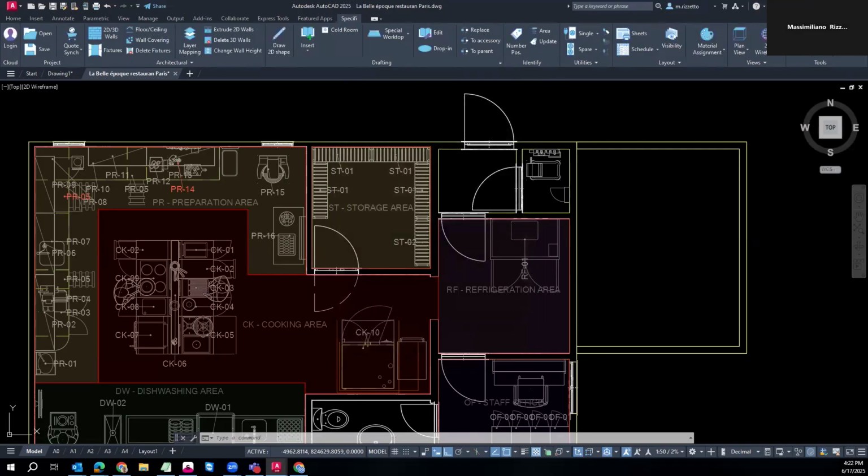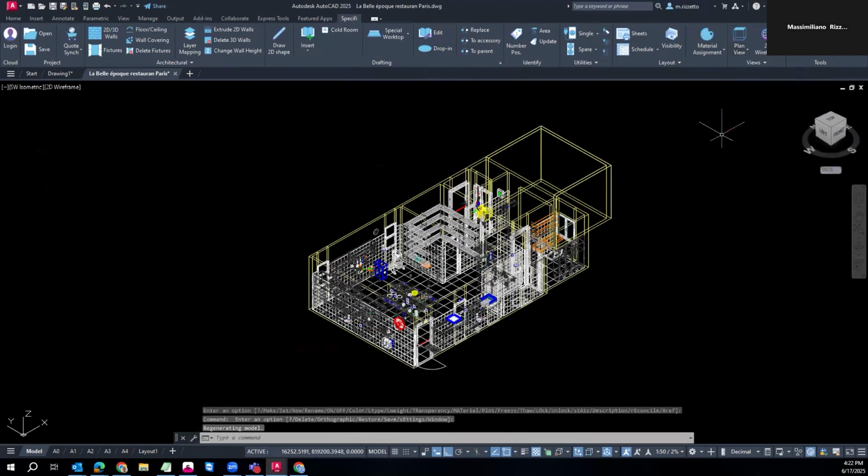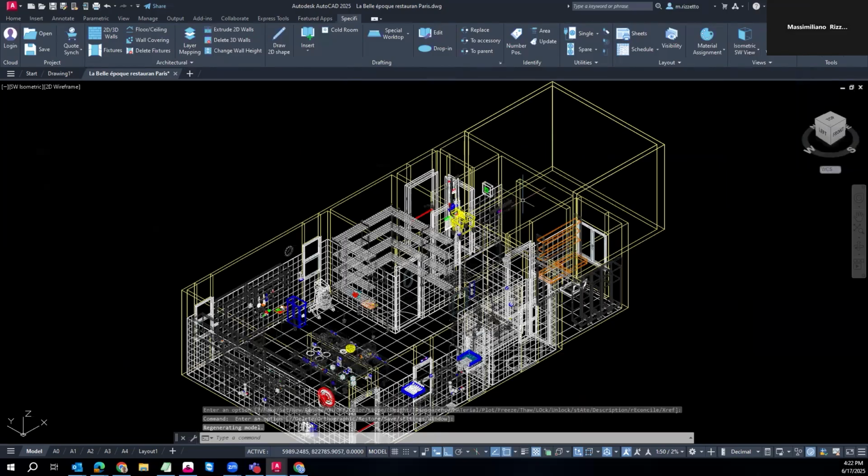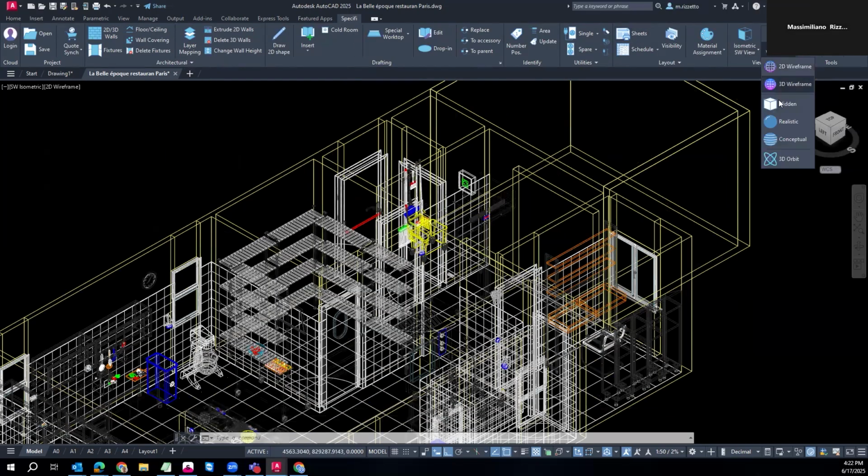Okay, and 0 insertion height from floor level. I can click OK. The software asks for external internal point, so outside, inside, just to cut our wall. It asks me where I want to place the hole. Okay, I can select a point over there along this, and we can see in 3D, we can also apply the shading, the realistic.